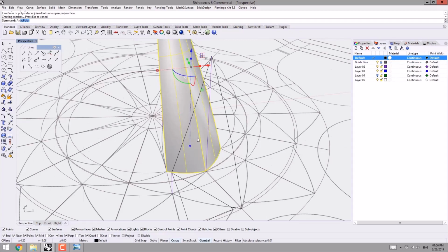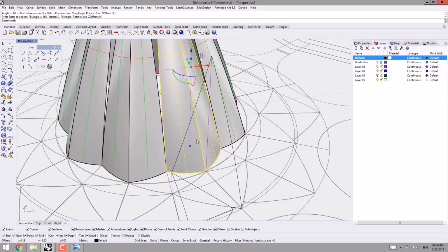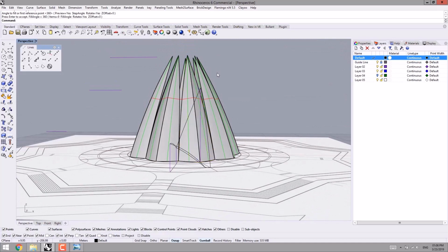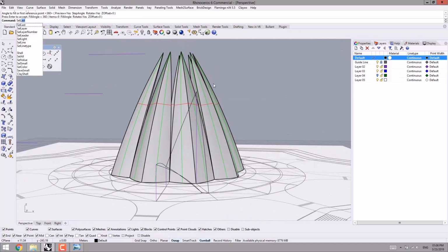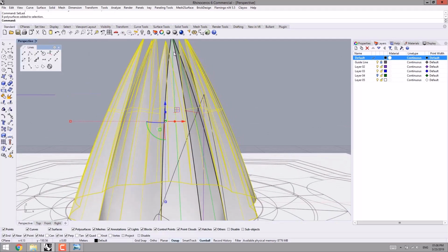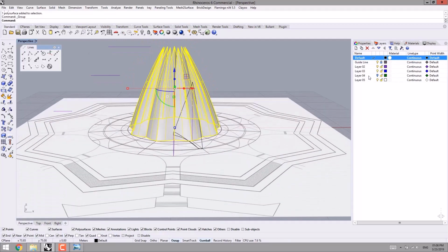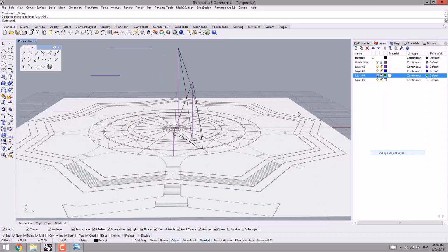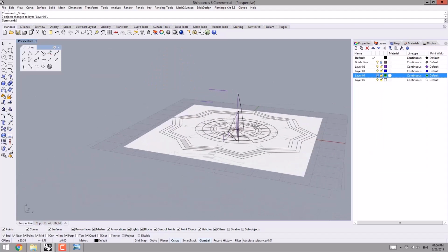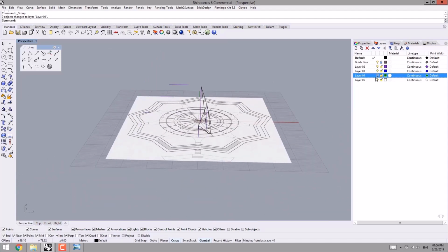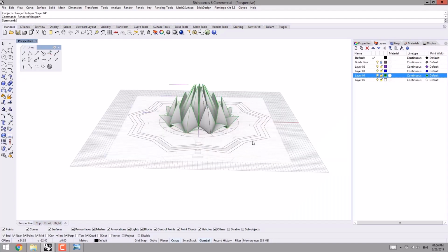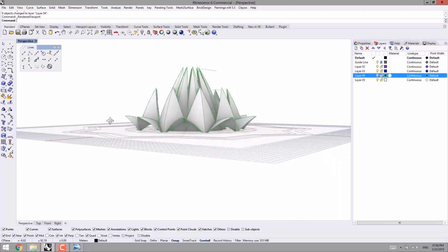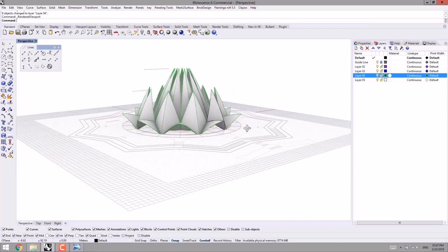I select the 2 surfaces, Control J to join them. Following that, array polar, 9 as number. Watch this. I select the items to group them. Hold down Shift, select, Control G, and then I assign them to the layer 4 by this way. Then I show the layer 4 to check the general model till now. Watch this.